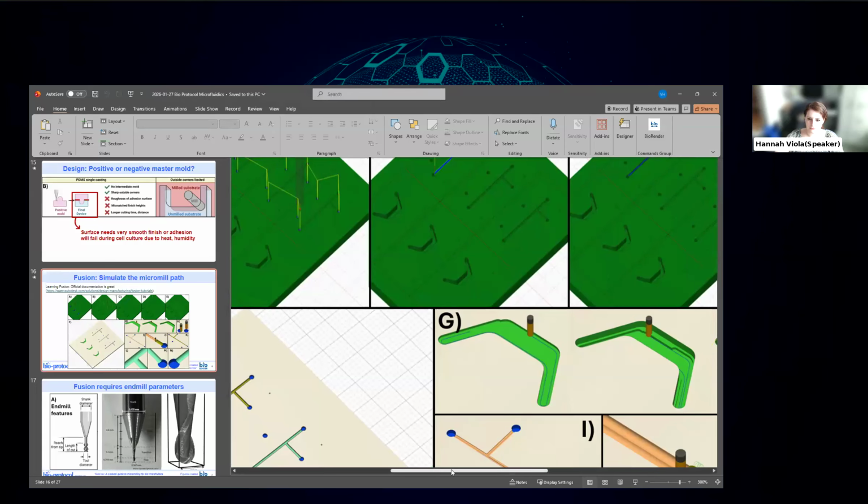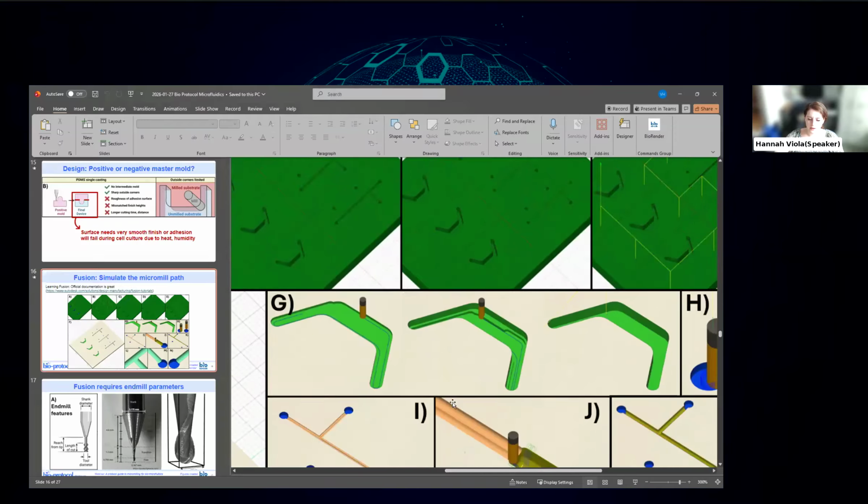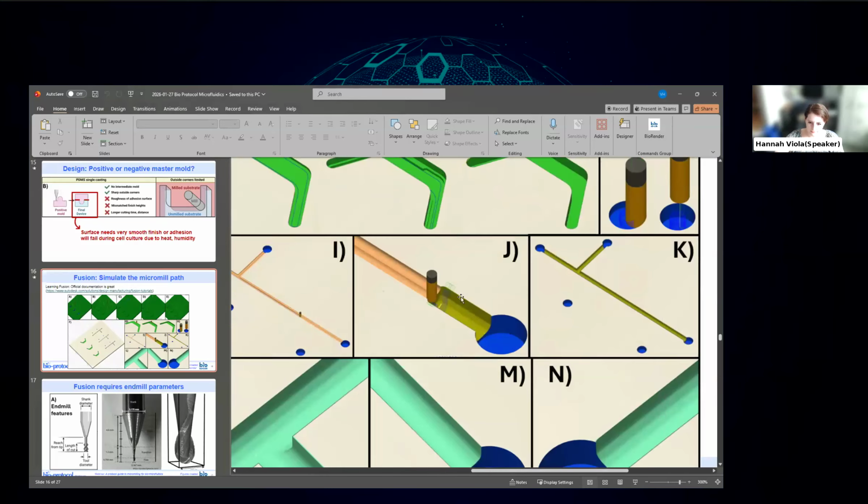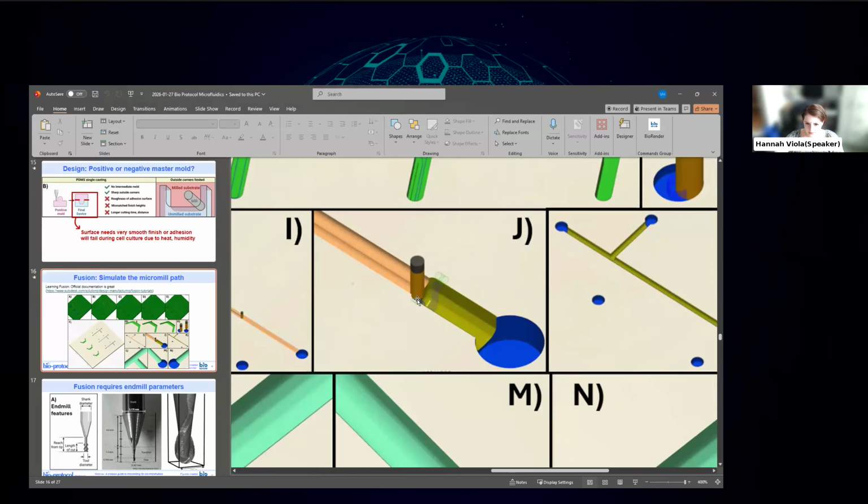So I took a smaller tool than my diameter. The first cut that I did, I went all the way across the channel with a bigger tool just to clear the material. But for the final surface finish, most of it I ended up doing this way with a smaller tool going back and forth. The reason for that was I did not want to get ridges. See this kind of longitudinal ridge? That's because I used a bigger tool and I wasn't trying to go all the way in, but I found this gave me a smoother surface finish with less artifacts when I did it like this.